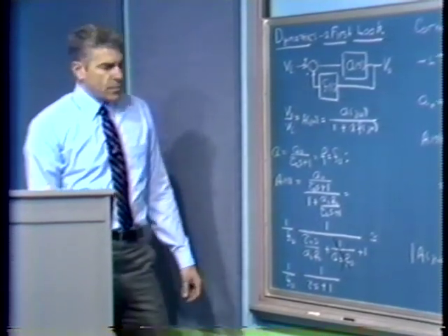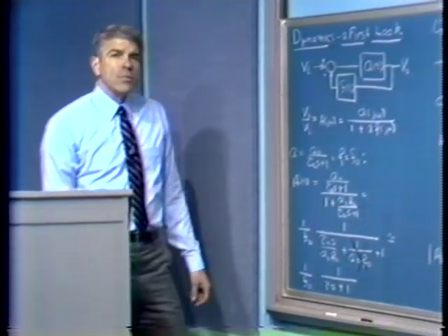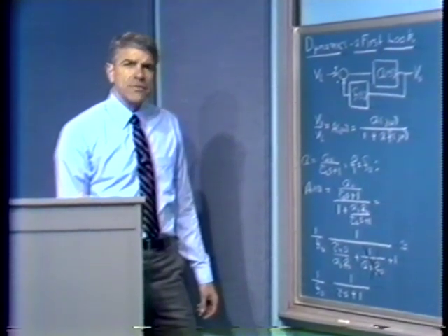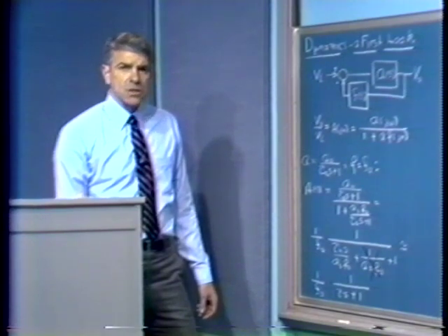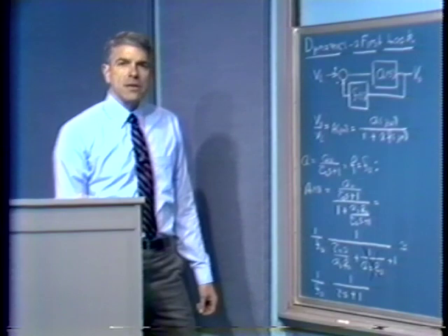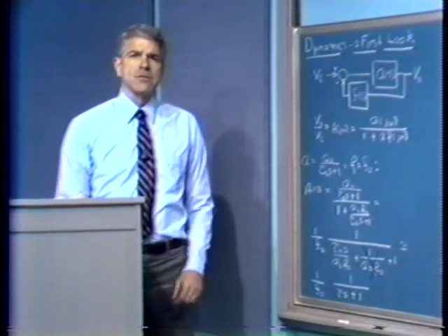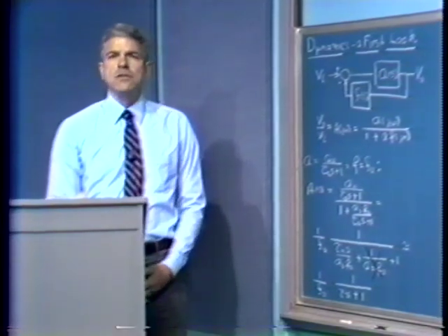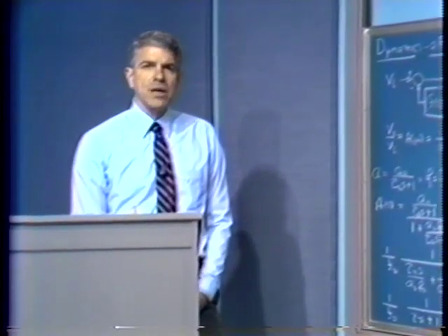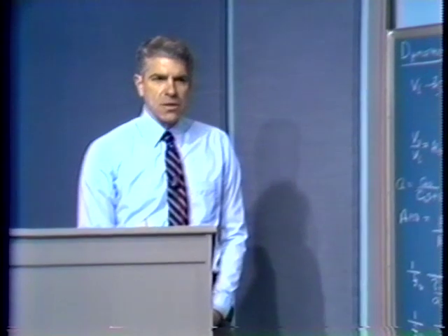Throughout the material that we're looking at, we'll be interested in the relationship between the transient response of our feedback systems and the frequency response of such systems. In particular, a very useful indicator of the performance of a feedback system is its step response. That's easy to determine experimentally. Remember that in order to measure a frequency response, we have to get a sinusoidal generator, we have to make measurements at a large number of frequencies. That's tiring and time-consuming, generally unproductive.